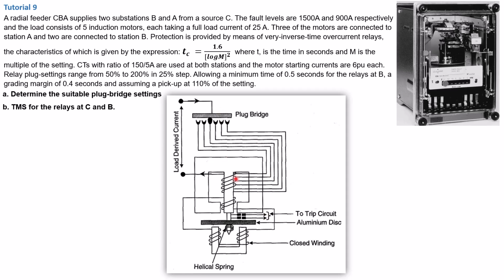Now, the other keyword that is also there is the minimum time. Look at it. It operates faster, but there is also a minimum time. As we start solving this problem, we're going to talk about actual tripping time and operating time. So there is a minimum time in which the relay has to operate. It's not going to trip before that time elapses.